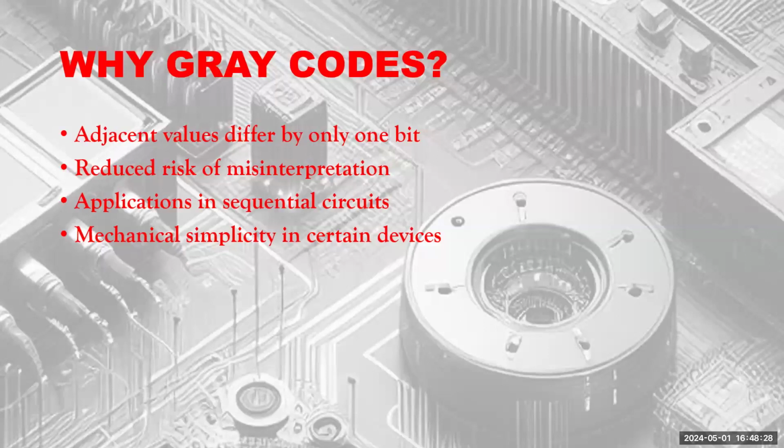There are other methods by which we improve things. There are error corrections, things like that involved. That's a separate subject. But gray code is for when you have to transmit a sequence of counts one after the other. That is when it's very helpful to switch from binary to gray code, so that a single bit transition is assured when we cross from one count to the next count. This additional information I just wanted to tell.